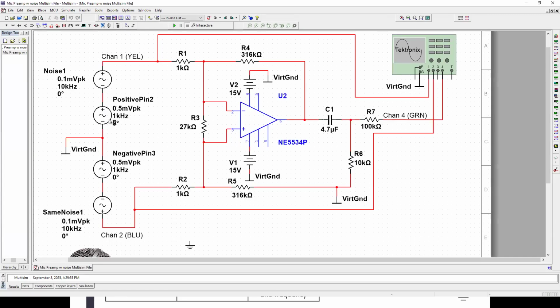All right. Now we still have that signal. And this signal and that signal, these are the same waveforms, it's just a simulation of a signal. So these two waveforms are out of phase going in there. They're going to be amplified as signal. And here's noise that goes the same way on both lines. So the noise goes in phase.